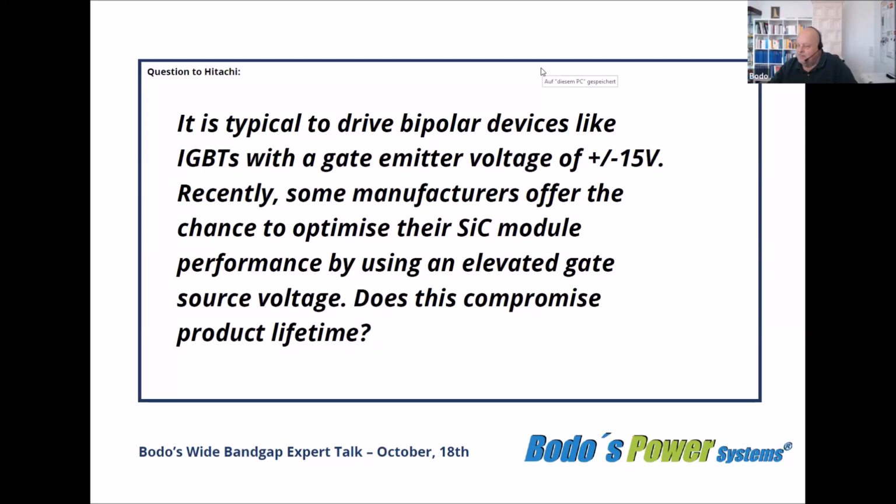Okay, thanks very much for the question. I'm Chris White, engineering manager for the Power Device Division for Hitachi Europe. The short answer really is no, it doesn't. This is really about optimizing losses, both conduction losses and switching losses. For example, elevating the gate-source voltage during conduction gives us good benefits in lowering the turn-on loss, but also lowering the conduction loss.